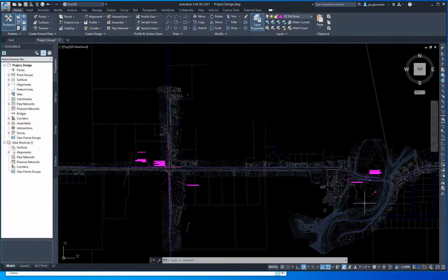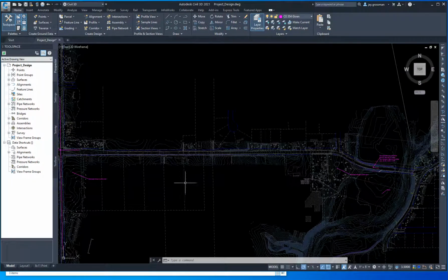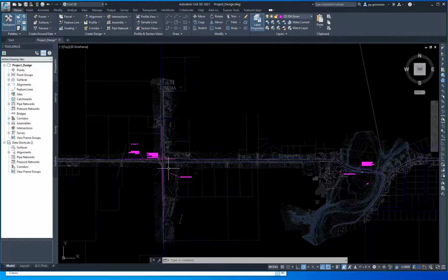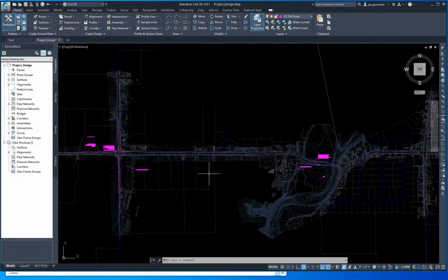Okay, that's I guess some brief things to get started and what we're seeing in this drawing. And so your first question may be, well, how do you start? So the process that we follow is first we design the alignment, and then we're going to design the profile. You have to do the alignment first so that you know where your existing ground is, and then once you're happy with your alignment, then we design the profile. And you can tweak them later.